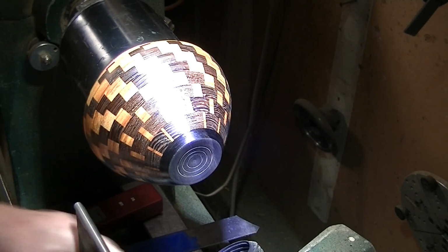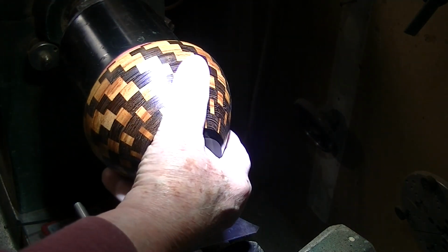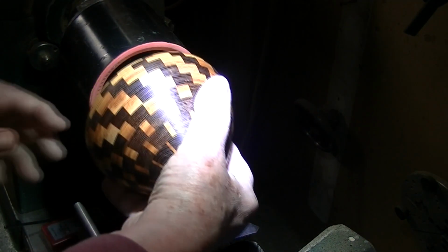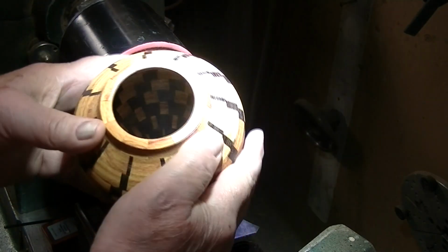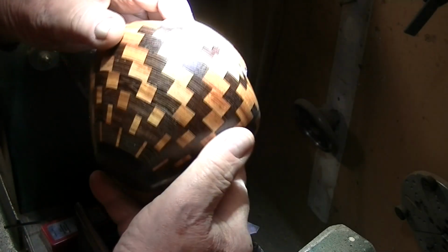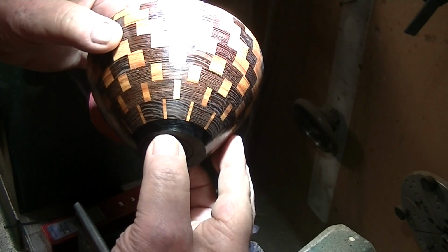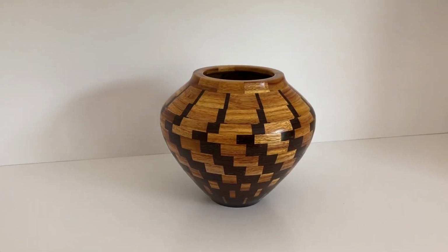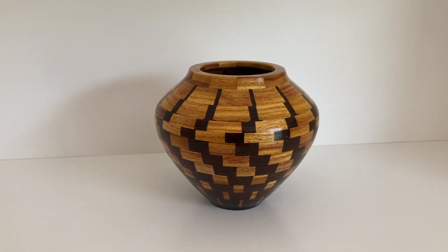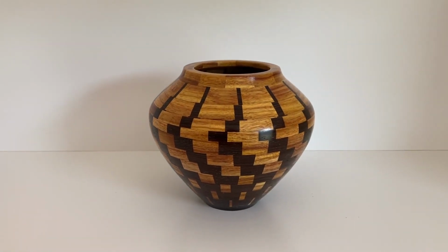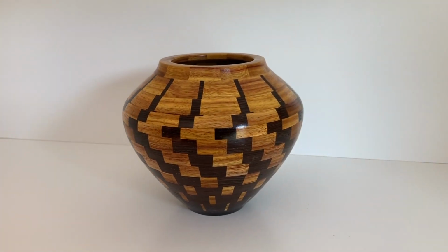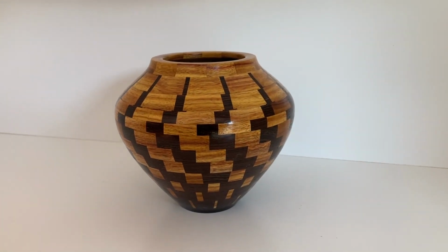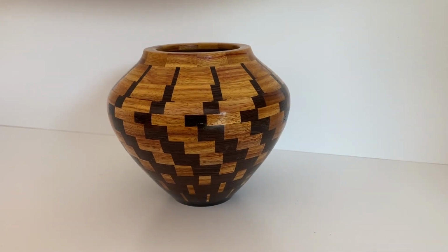So we'll take it off of the vacuum chuck simply by reducing the vacuum, turning off the pump, and the piece just falls free. And there it is, completed, done, sanded. I haven't buffed it out yet, and that's the last step I will do. And it comes out looking sort of like this when we get done. So there's all the steps I go through to build a project which is a simple segmented vessel, but with a number of varying thickness spacers.